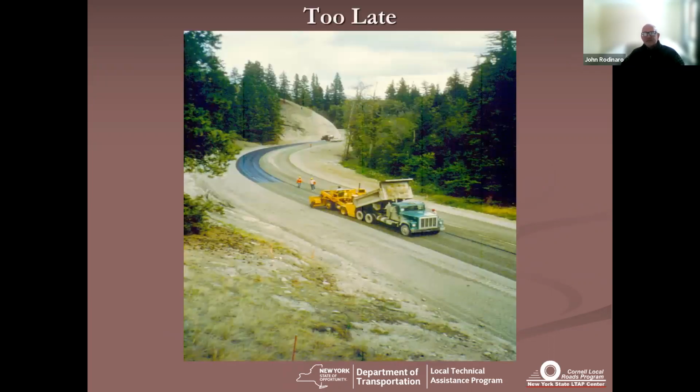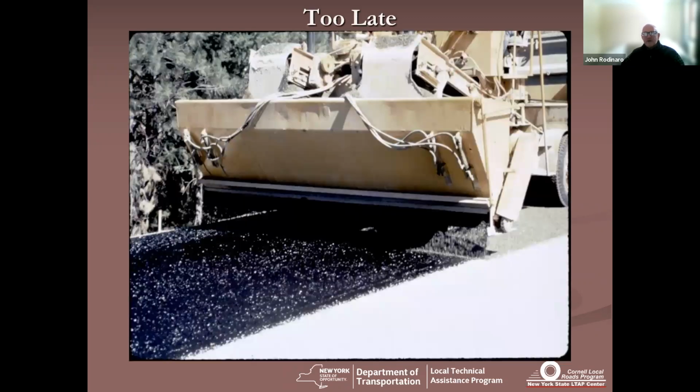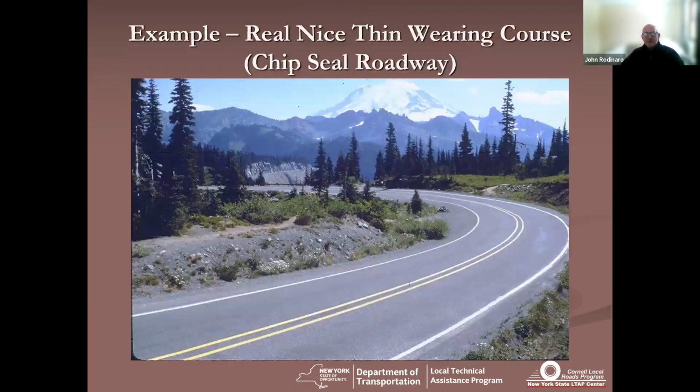And here's a case of it's too late. That emulsion is black already, and there's no way that aggregate's going to stick to the emulsion. Another case of too late. Looks like they're going to town, but that emulsion's black, and that aggregate's not going to last there very long. So you've wasted a whole lot of time and resource.